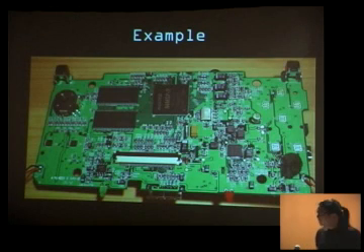You flip the board over, take a look at the other side, and say, okay, I see some buses here. These are the memory buses. This is the memory bus right here, so if I have to tap something, this is one of the places to start looking. This is the core processor, it's in the middle of the world. Here's a 32 kHz crystal. Here is a Maxim part. This whole circuit here controls the LCD bias. That's the LCD connector. This guy here is the VCOM amplifier for the LCD.